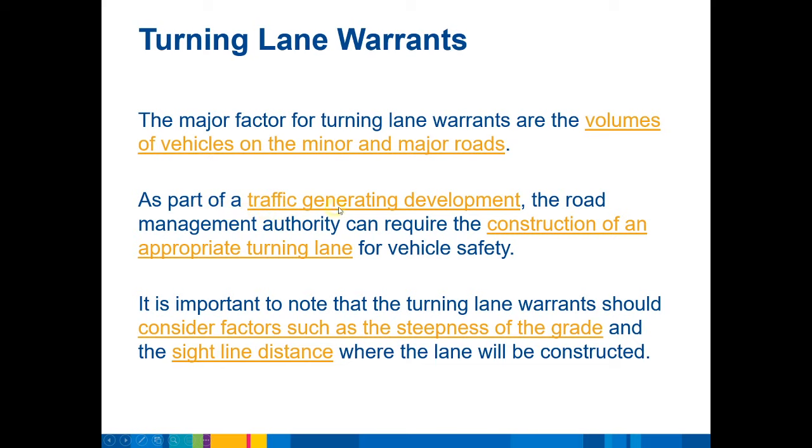As part of a traffic generating development, the Road Management Authority, which could be VicRoads if it's an arterial road, or it could be the City of Ballarat or the City of Yarra or any kind of local council if it's a local road, can require the construction of an appropriate turning lane for vehicle safety.